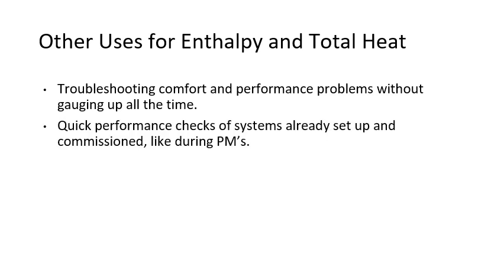You can also use these enthalpy and total heat checkups for quick performance checks of a system that's already been set up and commissioned, like during preventative maintenance calls. Now, you don't want to simply use an enthalpy and total heat check when you're starting up a system that's just been installed for the first time. Nor would you probably want to do it after making a major repair like a compressor replacement or having to remove the charge out of the system and put it back.